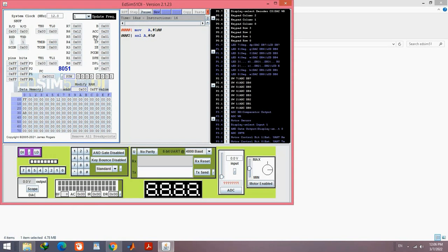So as you can see, the program counter is counting continuously because there isn't any end in the final statement. So it is continuously executing the memory, and the memory content now, if you check it here, is 0. 0 is the opcode of no operation in the 8051. So all of these no operations are now executing, but I don't want to execute them, so I'm pausing.